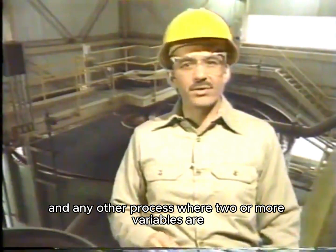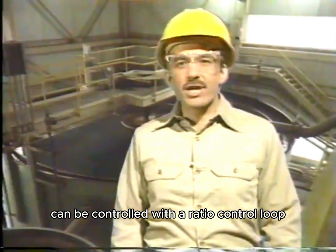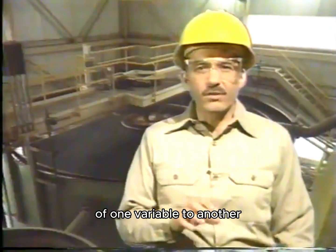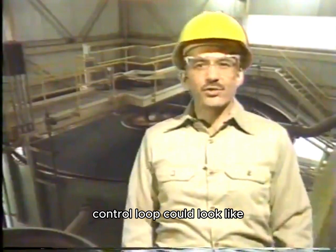Now, this kind of process, where two variables are mixed at a specific ratio, and any other process where two or more variables are combined in specific proportions, can be controlled with a ratio control loop. A ratio control loop maintains a predetermined ratio of one variable to another. Let's see what a generic ratio control loop could look like.